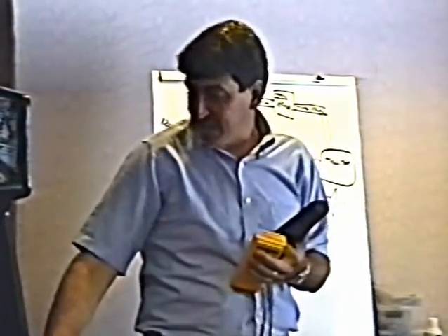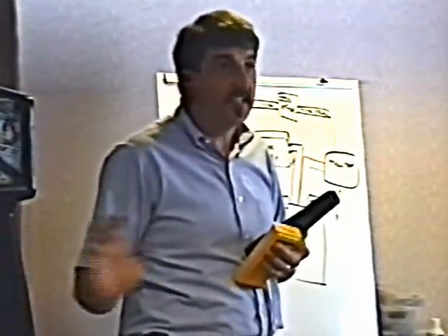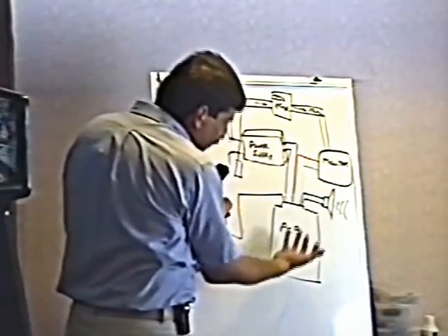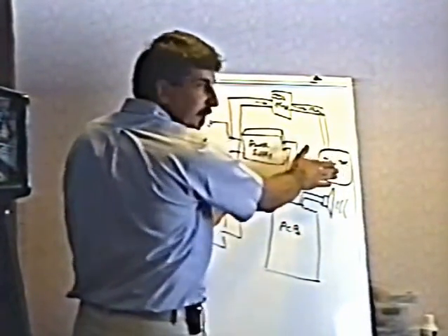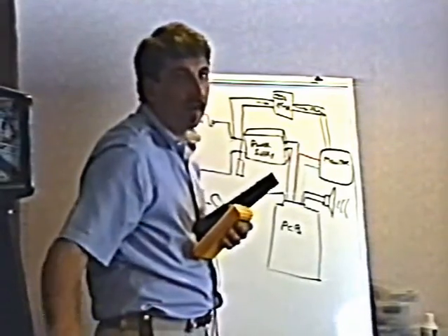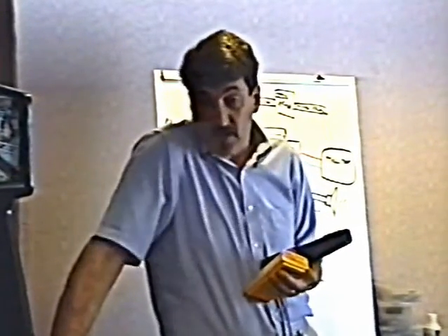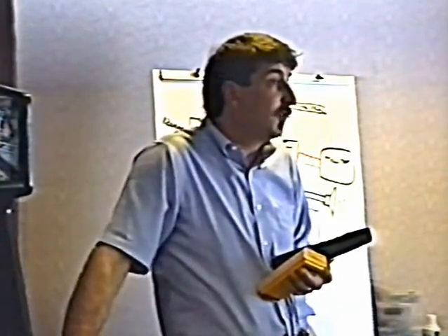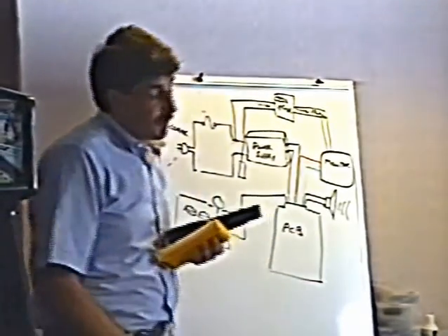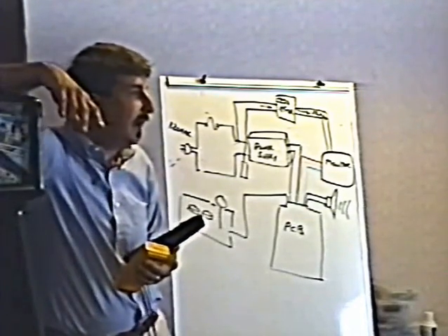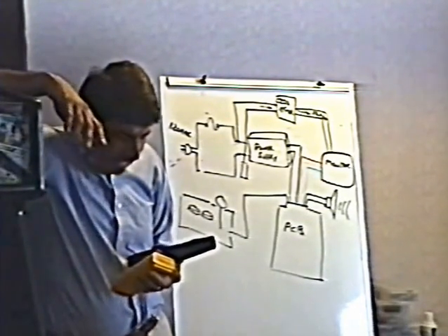The reason the monitor isn't showing anything is that the power supply is not powering the computer, so it's not putting out those red, green, and blue signals that go to the monitor, and that's why you're not seeing anything on the screen. Wouldn't it be really stupid to rip the monitor out and start working on that when there's nothing wrong with it? So by coining, I know it seems so simple. You coin up the game, you press the start button. You'd be amazed how many people don't think to do that. I mean, it's such a simple thing.